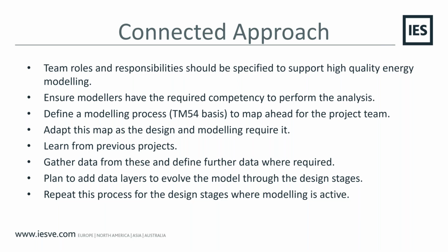Now, one of the things commonly discussed on energy modelling is, well, how do we gather the data together to ensure that it's available to populate and seed a TM54 model? Well, that's where there needs to be a process put in place to decide whose responsibility it is to gather something like the lighting data, the equipment data, what can be taken from previous projects or similar building types that you may have performed analysis on, and start to identify where the data gaps are that the team need to start to source from.